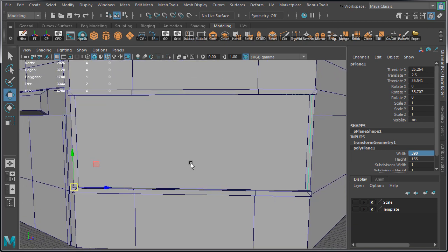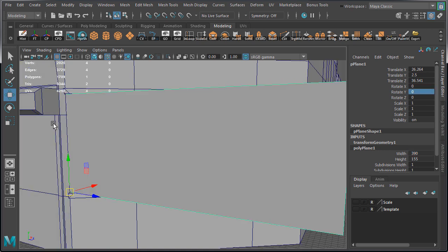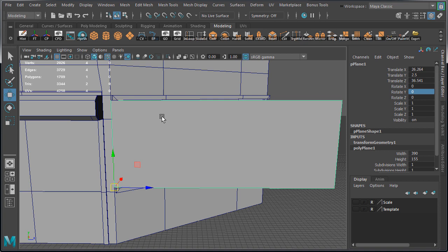We'll be able to adjust it more accurately so there's the same distance on each side when we're done with the window shutter. So we're going to keep this right now as is. We're going to reset the rotation back to 0 so this plane is straight because we need to model our detail and we're not going to do it when it's rotated at an angle into position. It will just make our job more difficult. Once we have it straight, let's go ahead and freeze transformations. We are now ready to model in the shutter detail.